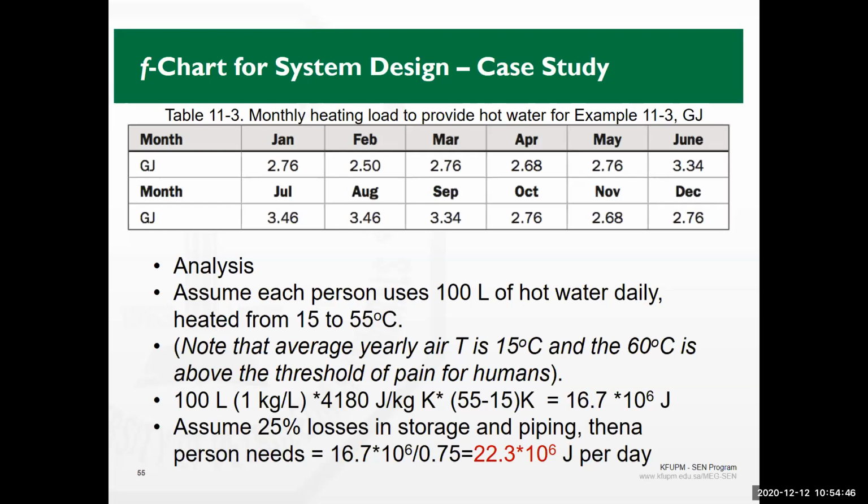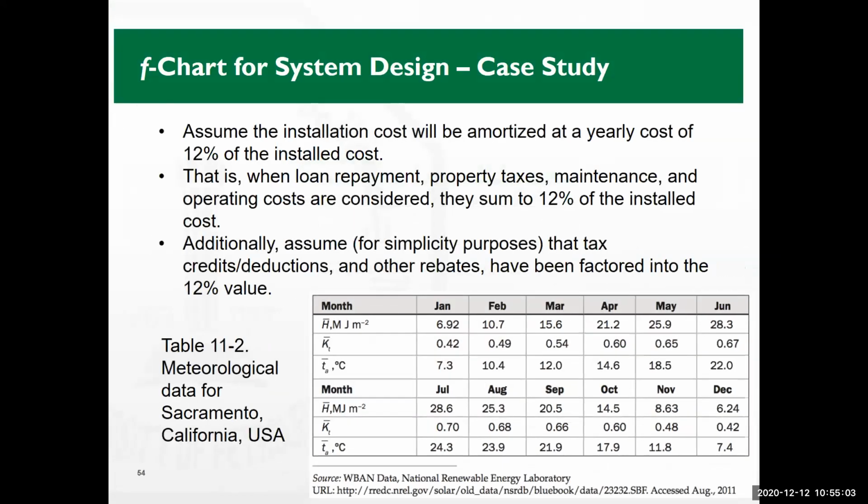You are designing anyway, and in your design you have the freedom to make assumptions as you are moving in. And at the end, having these values of T water in as 15 constant all the year, or changing according to the values that you have here, it is 7 in January, 10 in February, 12 in March, 14.6 in April, 18.5 in May. Sometimes it's less, sometimes it's more, so it may balance each other.